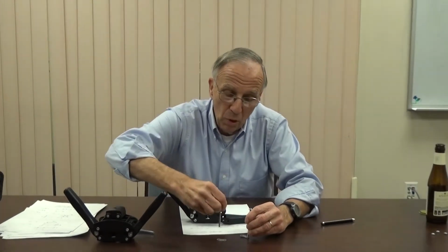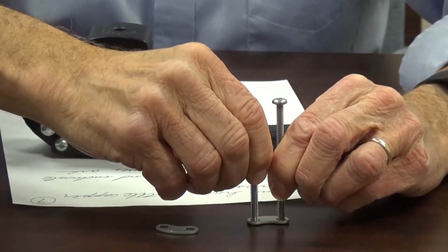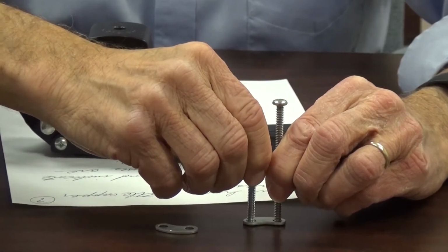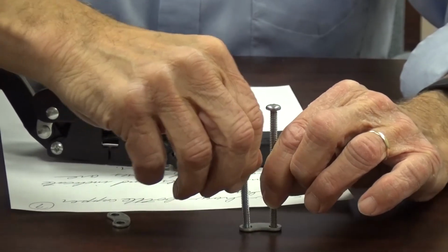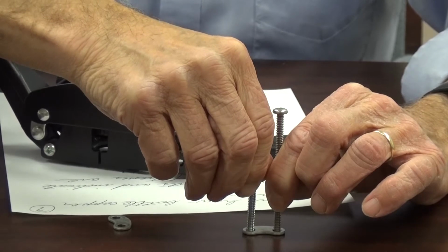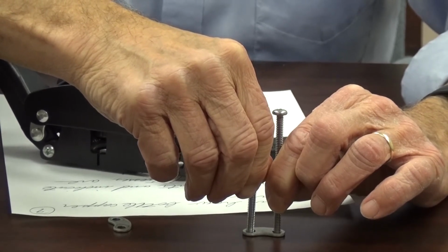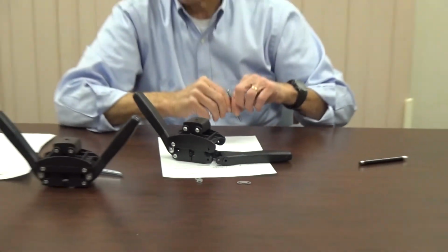Therefore, if we pull on them, I'm going to put the screws down here on the table and pull on them, the forces acting in the direction along the tabletop have to act through the two holes, and they have to be equal, opposite, and collinear. So this link is essentially, when I go to cap the bottle, in tension, just like the first example that I gave you in this video.